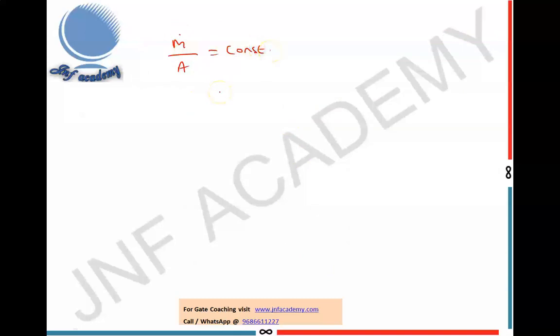That is your mass flow rate per area, and it will be some value. Then you consider your flow to be choked. There is no other opportunity for you to increase this m dot by A.